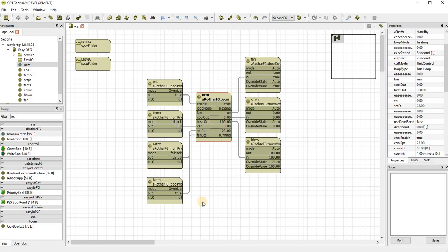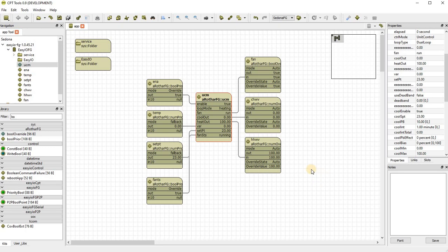Again, it was well out of the ordinary, so we never applied it, and since that project, which was probably about 10 years ago now, we've developed this UCM and modified the proportional effect, which would probably have worked on the kiln anyway, because it kind of acts as an anticipator, just like a derivative is supposed to.